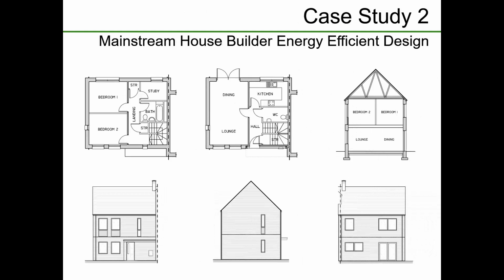This one is 500 and some homes, also in the north of England. Traditional masonry construction, but with an enhanced specification. So 100mm PIR in the floor, in the walls. It uses a composite flooring system where it's beam and block, and you've got a large amount of EPS, and then you pour concrete over the top of that, and a good amount of insulation in the roof.